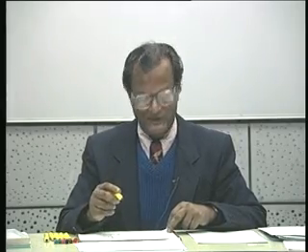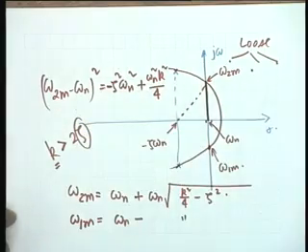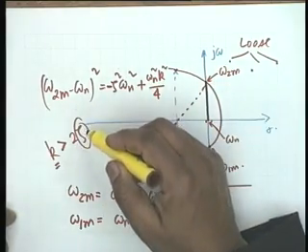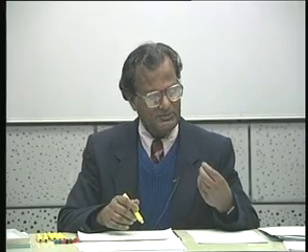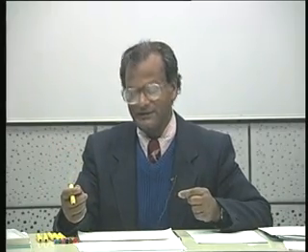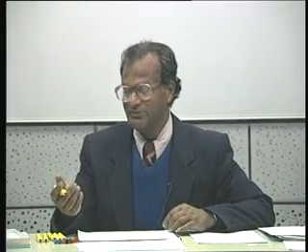Quite right. Now, however, a practical engineer will not try to do that, because he doesn't want zeta greater than 0. This is inevitable. You cannot make an inductor without a resistance, because the wire that you are using to wind the inductor has a certain resistance. You don't use an extra resistance unless you want to shape the curve.